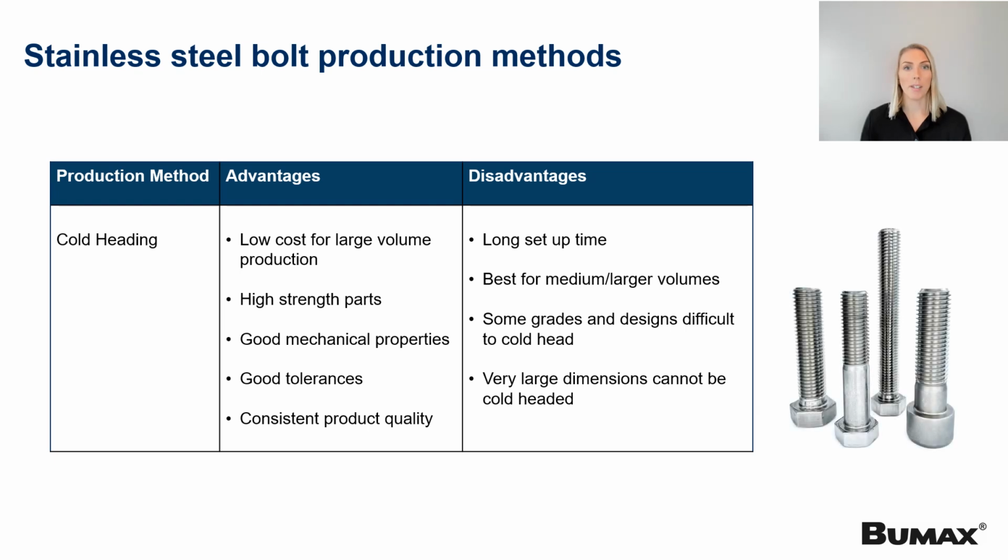Cold forging is a metal shaping and manufacturing process in which wire or bar stock is inserted into a die and squeezed into a second closed die. Cold forging is an efficient and economical metal deforming process for production of high volumes of parts at low cost. Unlike hot forging, cold forging shapes and deforms bar stock at room temperature using localized compressive force into a desired shape.